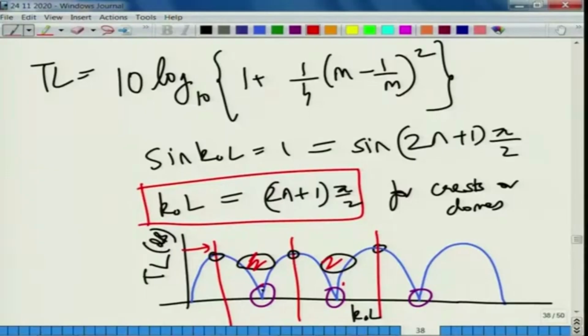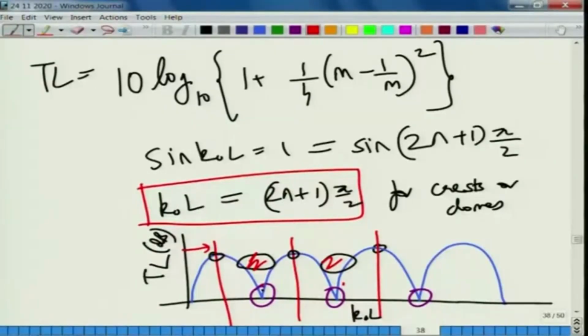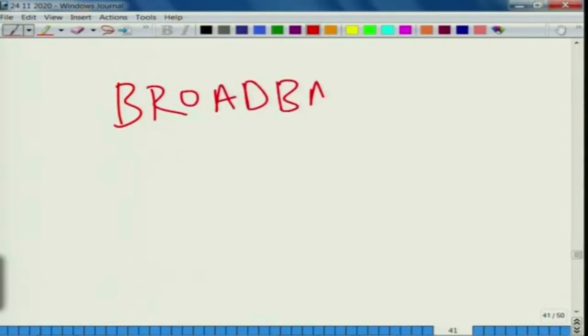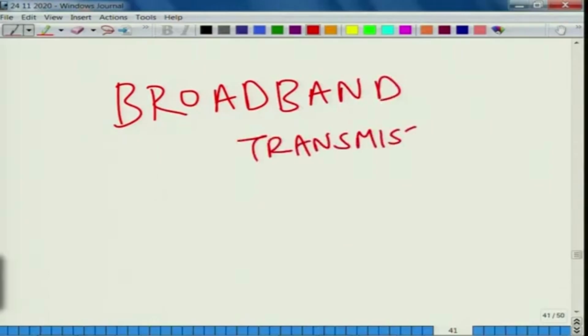So, what does one do to solve this problem? What does one do to design a muffler that is effective for automobile or exhaust engine noise which is running at different RPMs? One principle, the idealistic situation, would be to design a muffler which should produce a broadband transmission loss. So, this is the term that we are using perhaps for the first time, so let me write this in bold and in capital: broadband transmission loss, or also insertion loss, broadband, or also known as broadband performance.